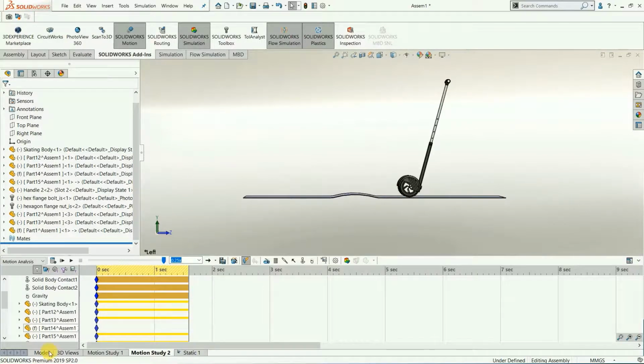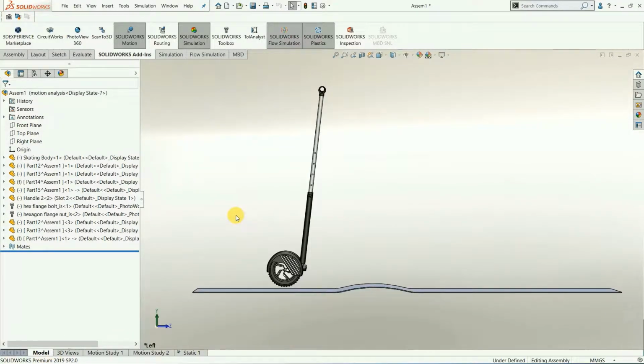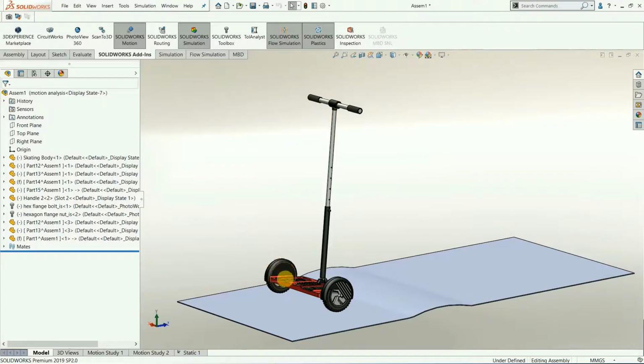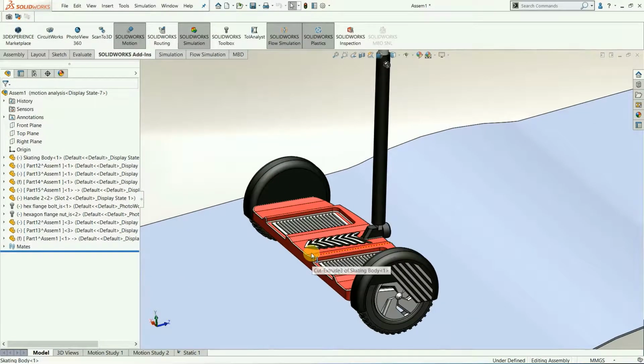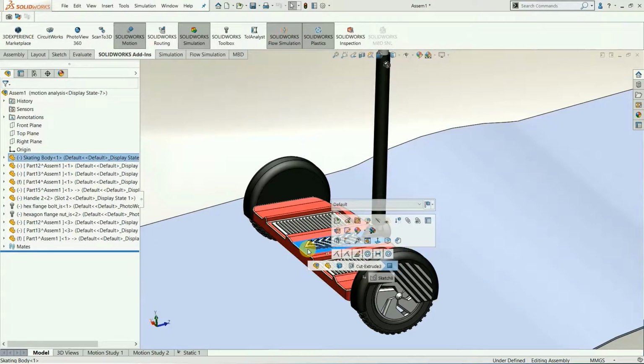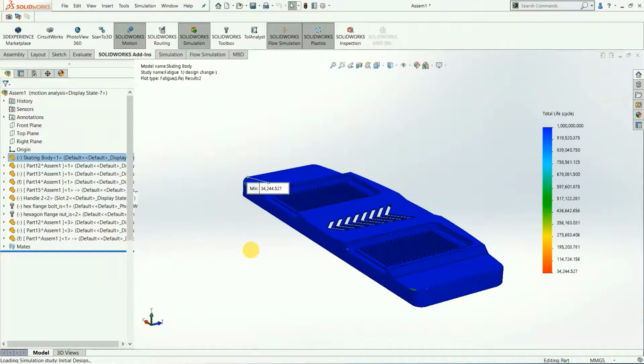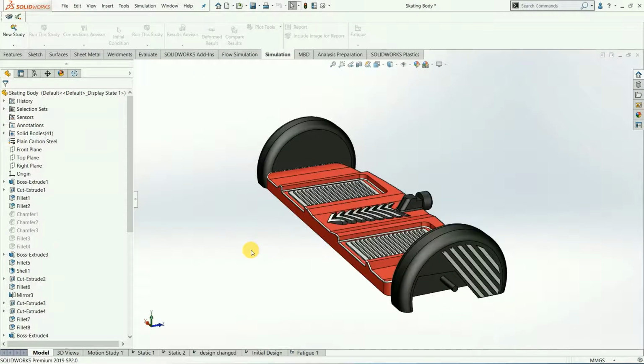I have seen these kinematic conditions, like how much torque is required and whether the CG is maintained in my model or not. And now I need to validate whether this base platform withstands my given load or not. So let's do an FE analysis. It's a finite element analysis to check whether this withstands the given load and where the weak regions are, and whether I need to go for a redesign or whether it is over-designed or not.